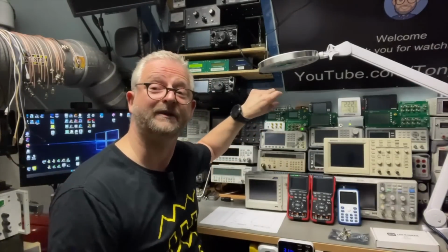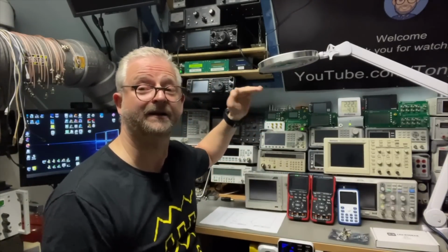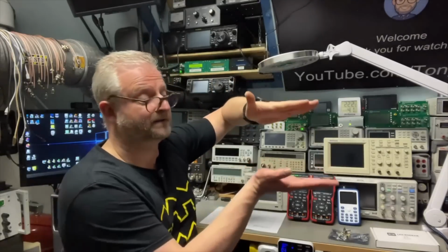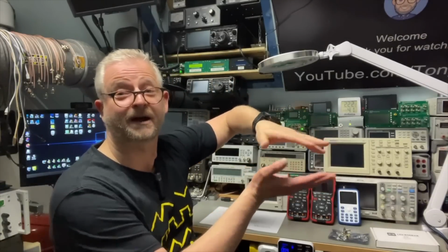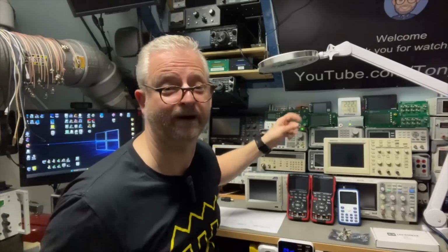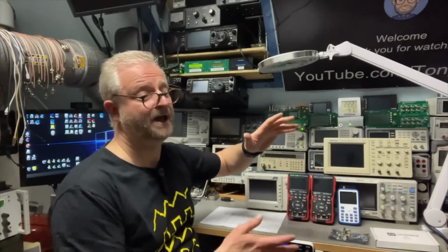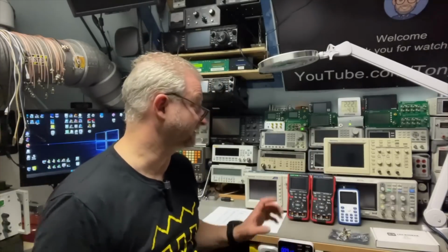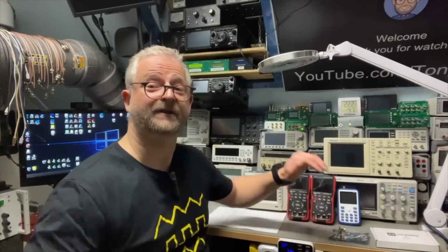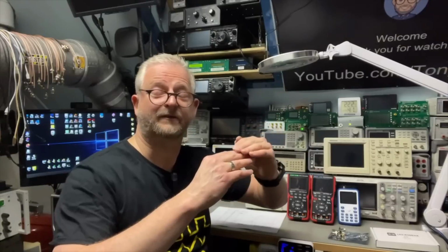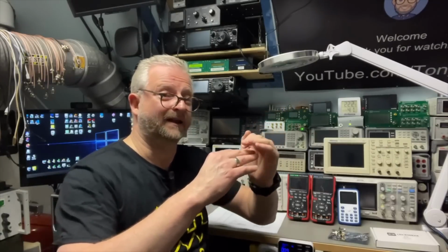You just set the frequency and then go higher, higher, higher, and at some point you see that the amplitude will just go down. If you are at about minus 3 dB or 70%, then you could say, okay, this is the limit. Then, of course, you also have the Risetime, and that is the test that I like to do. If the oscilloscope cannot rise enough from 0 to 1 volt, then your square waves start to look like a sine, because it just goes like this, as it cannot rise fast enough.